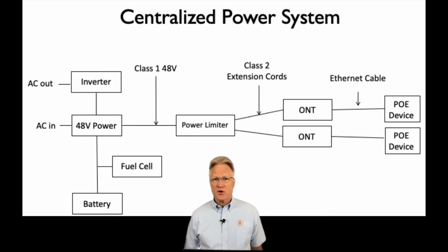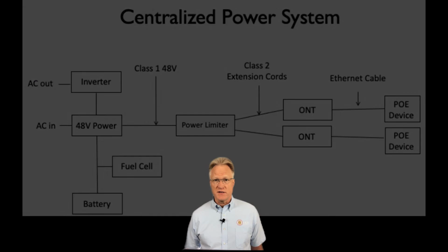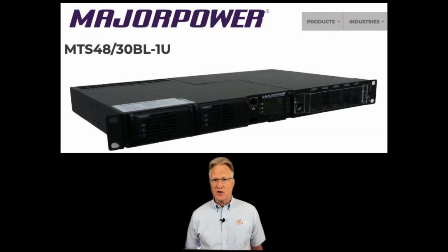946 suggests creating a diagram showing the batteries, chargers, DC panels, and all connected loads. Consider future growth as well as redundancy. The effects of special loads like inverters and DC to DC converters need to be well understood, as they will affect the DC bus from both current and voltage ripple standpoints, as well as its transient behavior.